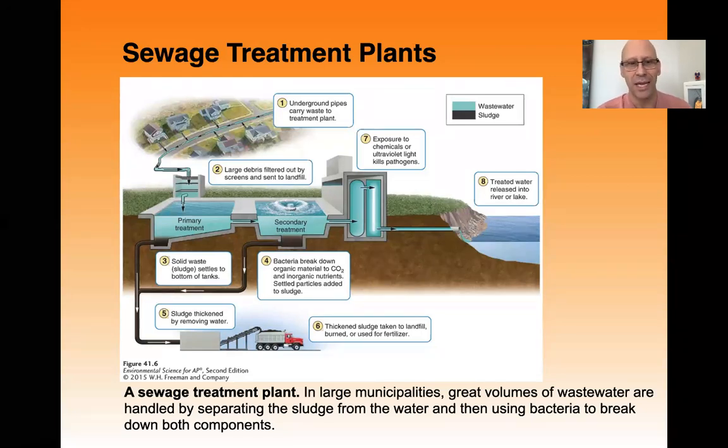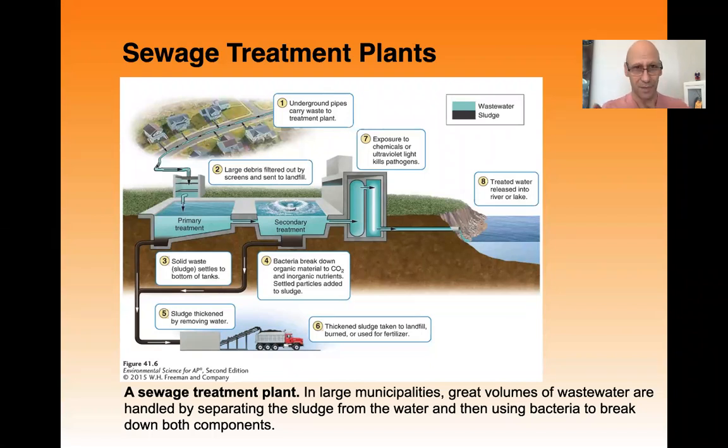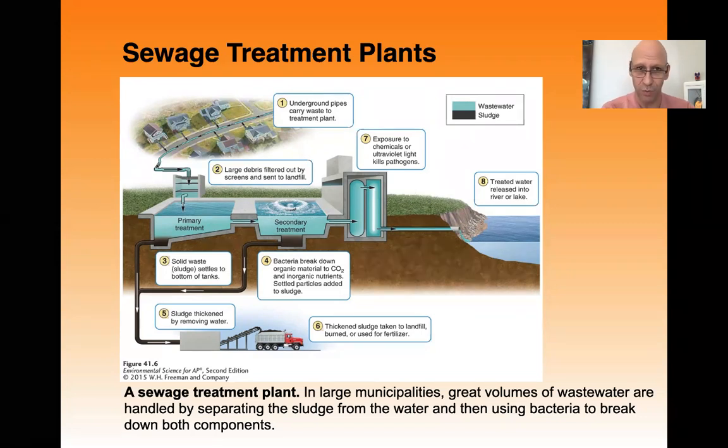And the way they do that, if you notice where this says secondary treatment, it almost looks like a little fountain. What they do is they feed that bacteria some starter, and then they give it lots and lots of oxygen, and the bacteria colonies explode, and they essentially feed on our waste. So by the time they're done, there's really nothing left other than bacteria. So you have to deal with the bacteria then. And the way you deal with the bacteria is you just remove the oxygen, and then the bacteria die.